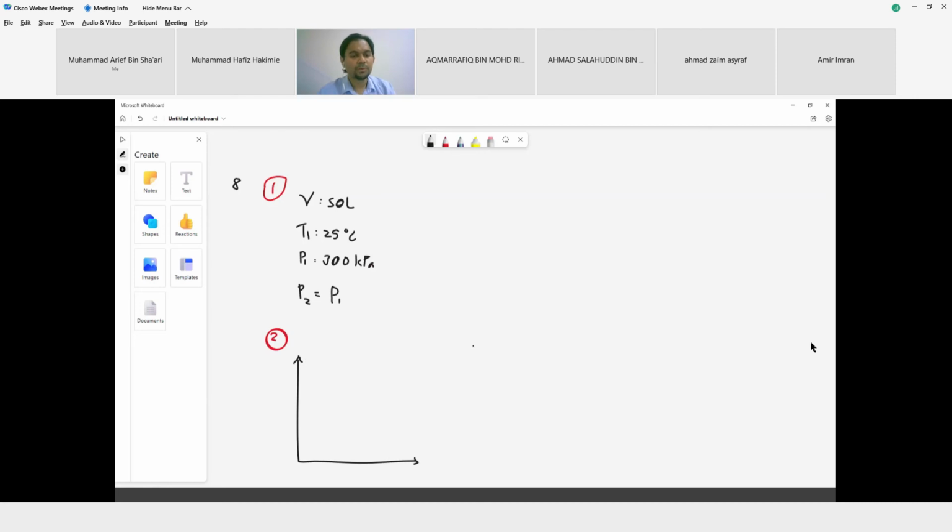So in this case, pressure and temperature are given, both are given. It's up to you, as I said, you can draw a PV or TV diagram. Since pressure and temperature both are given, for me, I prefer to draw P versus V. This is pressure. Step number 3, transfer all the information given.